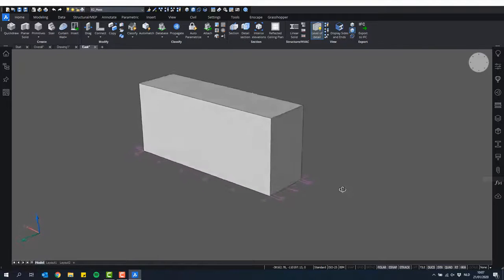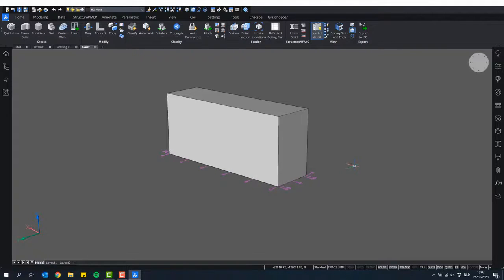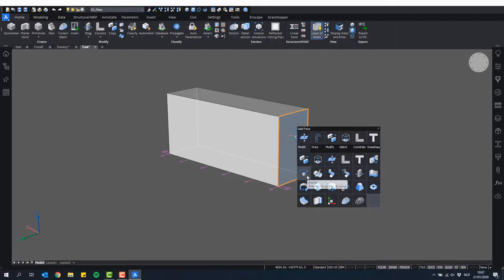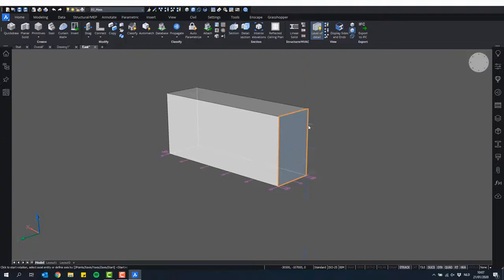The first thing I'm going to do is rotate some of these faces. As I said earlier, when I'm modeling, I usually have my face detection on, so I will leave it like this. I want to rotate this face around this axis. So I'm going to highlight this face, and in the quad under the Model tab, there's this Rotate tool. If I click this tool, automatically a yellow widget appears. It basically shows you the direction and the axis of rotation. So I want to rotate this face around this axis here.